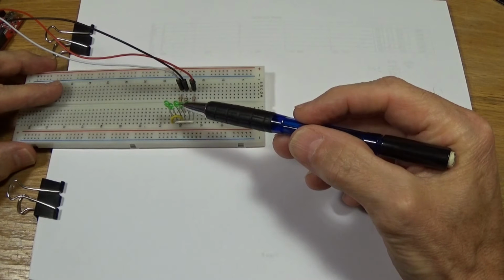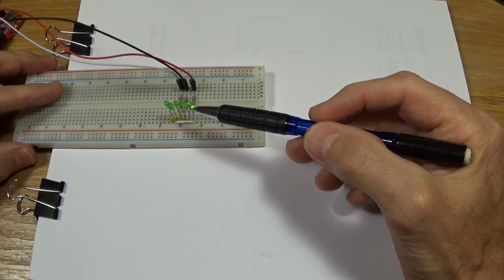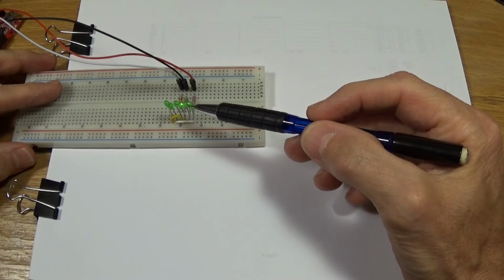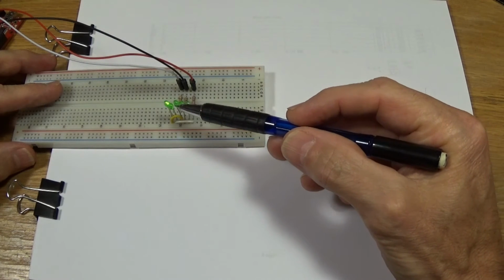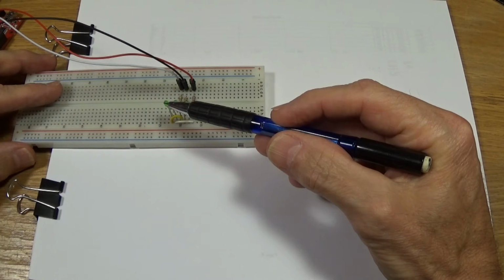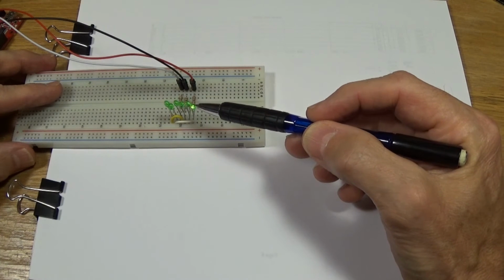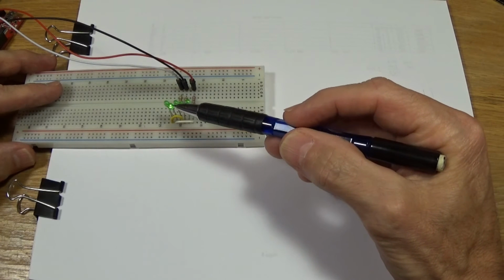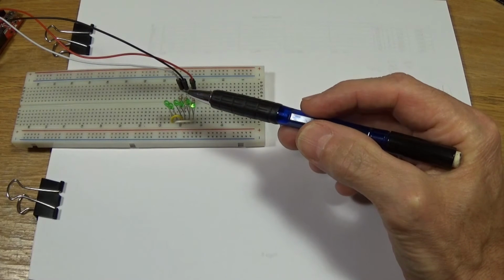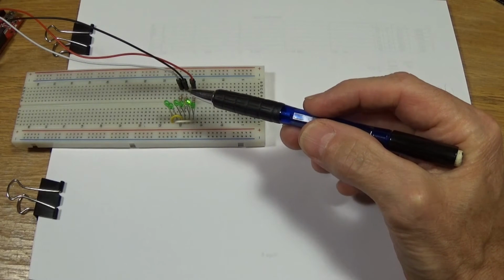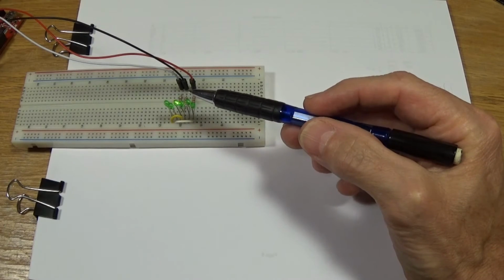So in this case there could be 6 states, and the state machine will just keep track of what state it's in, so it can switch to the next state, which then would turn on a different LED. And then when it gets to this last state, it'll swing back around and then switch on this LED, going back to the first state again. And in between each of these LEDs and this last state would be where you would do something else with the microcontroller for up to 10 milliseconds.